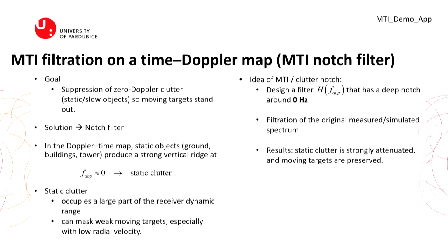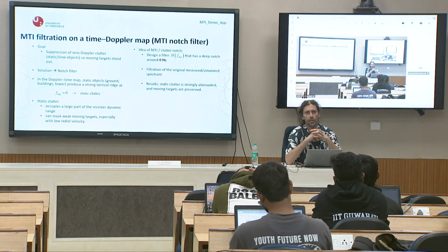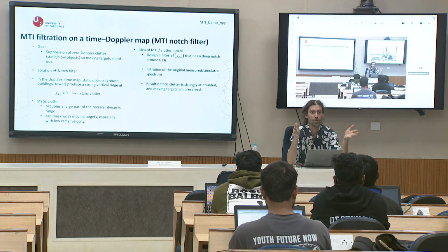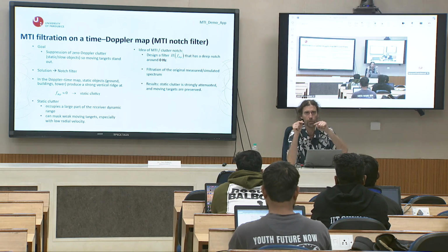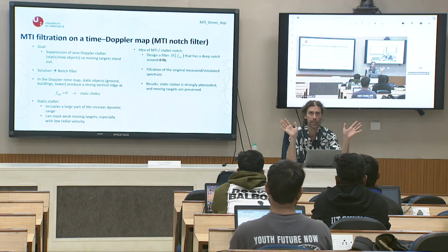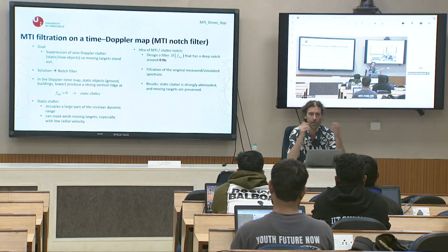So imagine that you have, okay, some example, a UAV that is not moving, just recording something, which is forbidden, but it is in the same position. Of course, there will be rotation of blades, but this is micro Doppler. And on a higher distance, the micro Doppler could be masked because it is not such a big reflection. It is the periodicity of micro Doppler that you can recognize. If you recognize it, okay, you will detect it. If not, it could be almost like static, if you get my point.